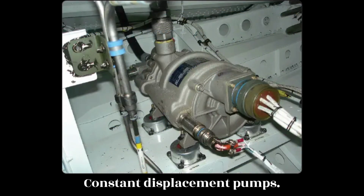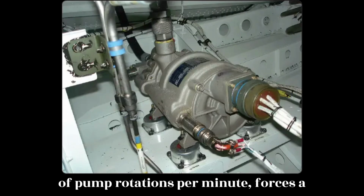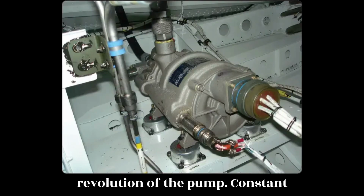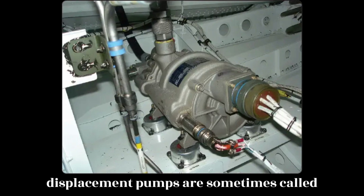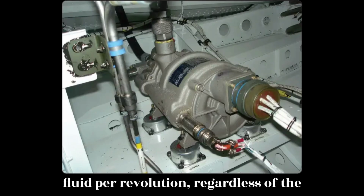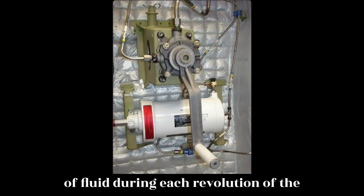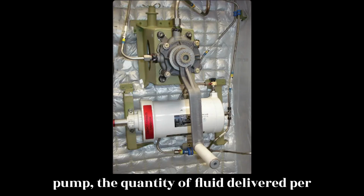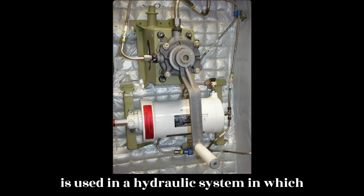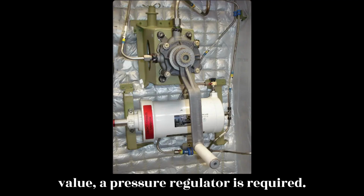Constant displacement pumps. A constant displacement pump, regardless of pump rotations per minute, forces a fixed or unvarying quantity of fluid through the outlet port during each revolution of the pump. Constant displacement pumps are sometimes called constant volume or constant delivery pumps. They deliver a fixed quantity of fluid per revolution, regardless of the pressure demands. Since the constant delivery pump provides a fixed quantity of fluid during each revolution of the pump, the quantity of fluid delivered per minute depends upon pump rotations per minute. When a constant displacement pump is used in a hydraulic system in which the pressure must be kept at a constant value, a pressure regulator is required.